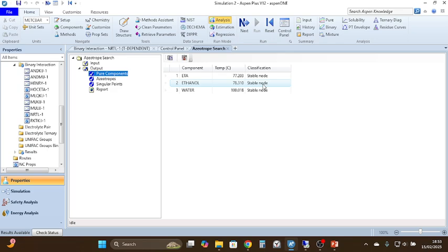The correct term that you can use is it is a point of equilibrium. A point of equilibrium means that these are the boiling points that are given. If you are not heating the system or disturbing the system and you are keeping the system at that particular pressure, that is 1 atmosphere or 101,325 pascal or 101.325 kilopascal, then the boiling point of these components is fixed.